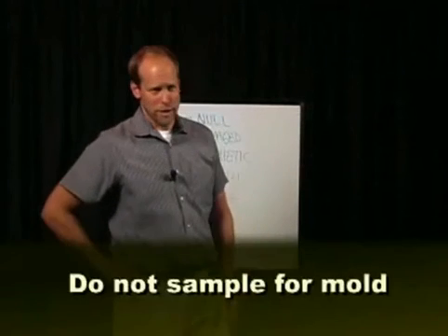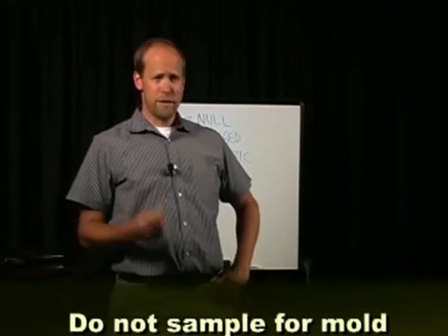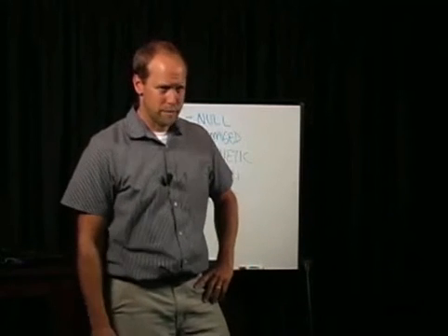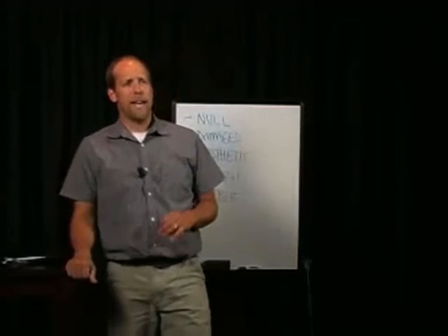Let's go over the do not sample for mold section. Do not sample for mold when a person occupying the building is under a physician's care for significant health effects attributed to mold exposure. A mold inspector should not be in conflict or dispute with any health professional by confirming or denying the absence or presence of mold and discussing the potential health impact from mold exposure. Consultation by a health expert should be recommended.